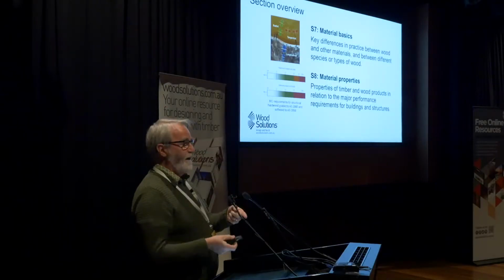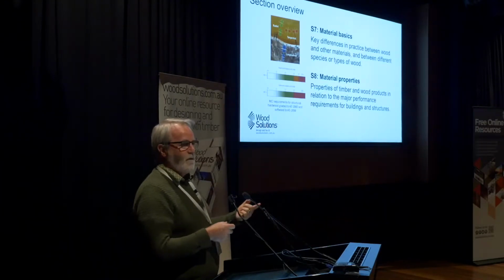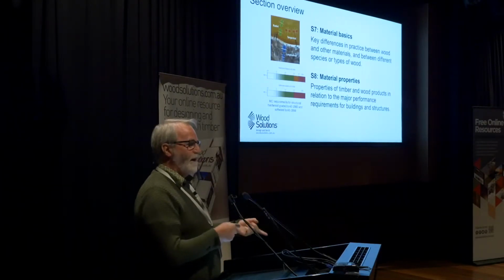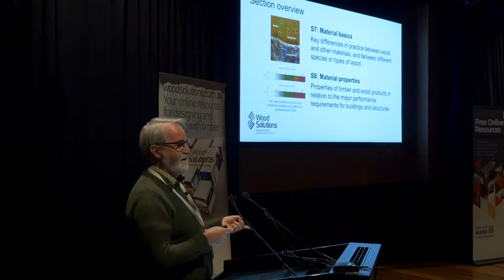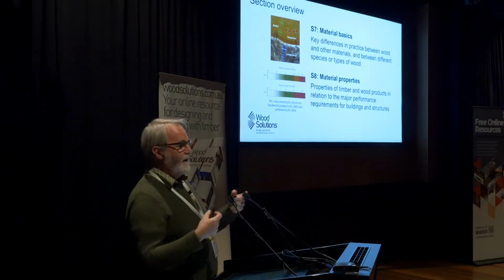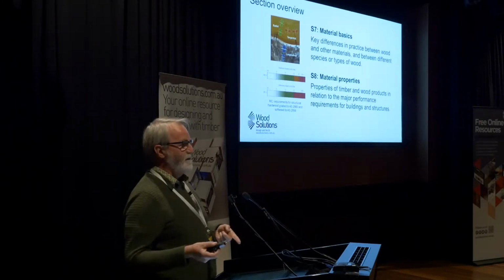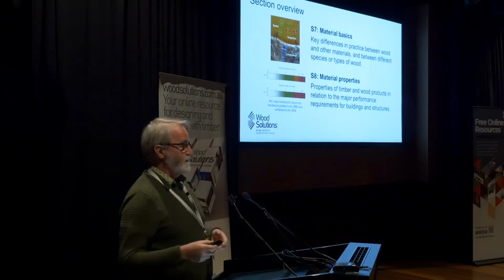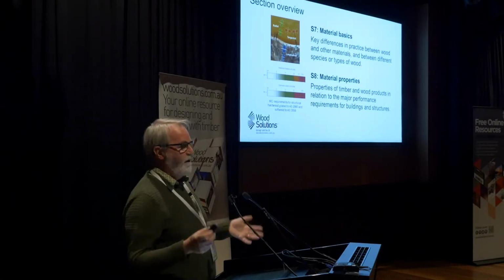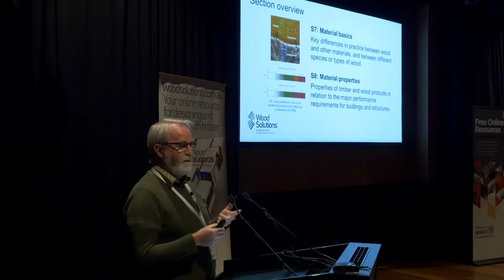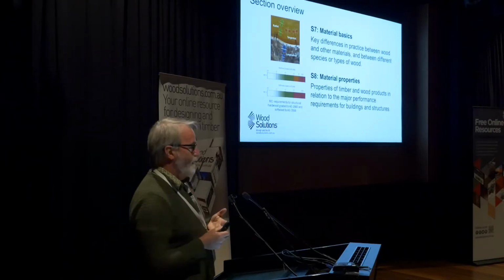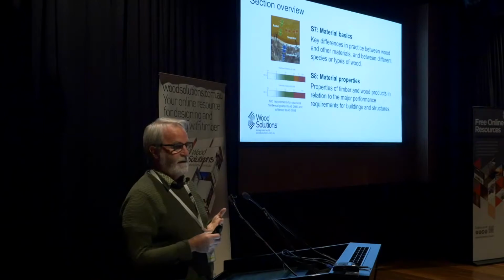Now, unfortunately, wood's different, because with wood, the tree grows what it wants based on its genetics, and we try to harness that genetic output to do different things, which means we've got products that are highly variable. They're highly variable, they're hygroscopic, they're anisotropic.